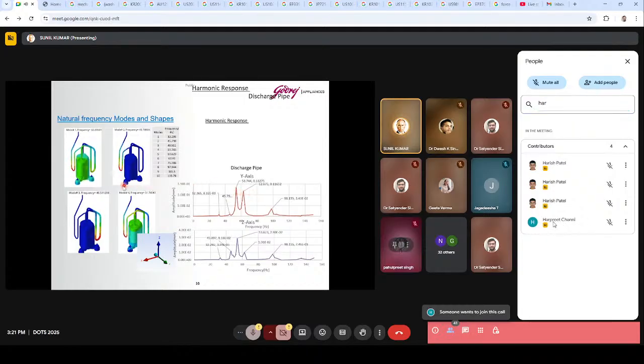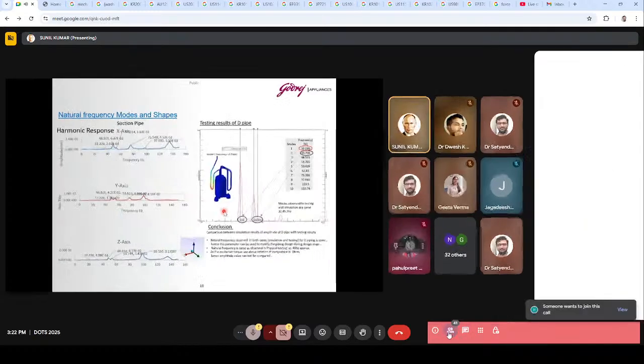Another method is we put load cells below, in place of the rubber grommets, and extract the force value. We put this force value in here, and we extract the exact vibration which we observed from the actual testing. I'll show you it in the end in a hands-on.